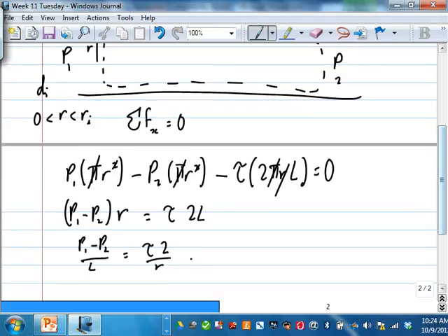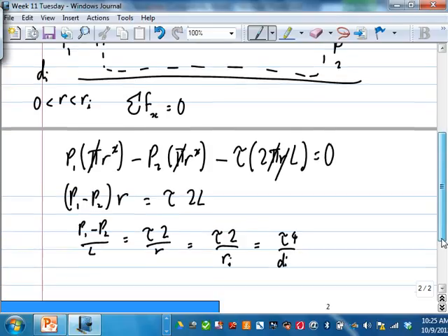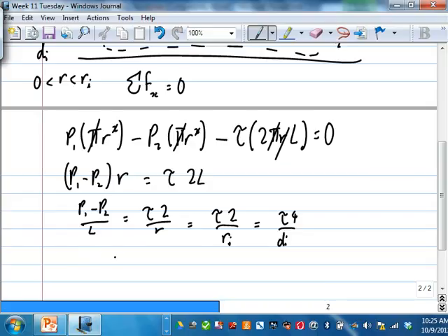So if you take this all the way out to the wall, you can take R to Ri. We can take that shear stress, or shear stress at the wall. This is the wall already. Subscript w means at the wall, is equal to Di delta P over 4L.